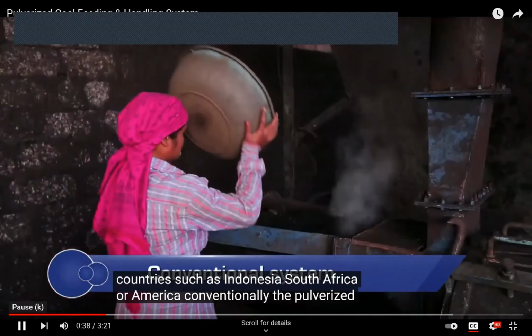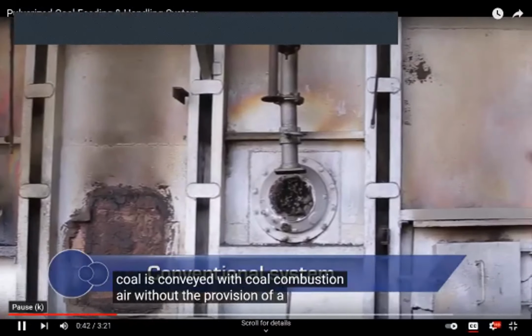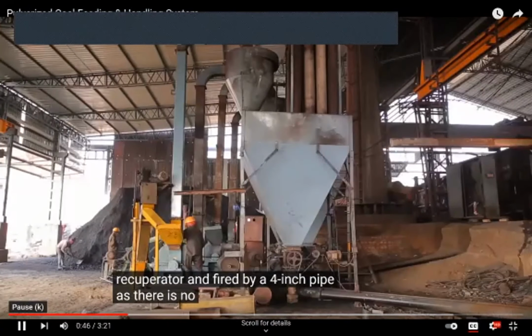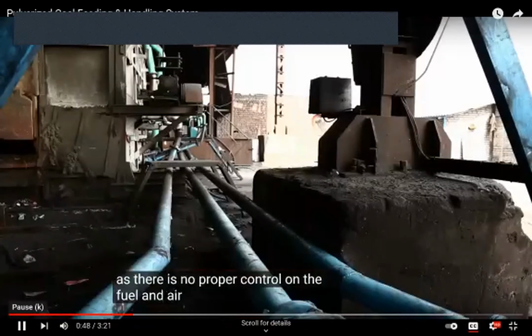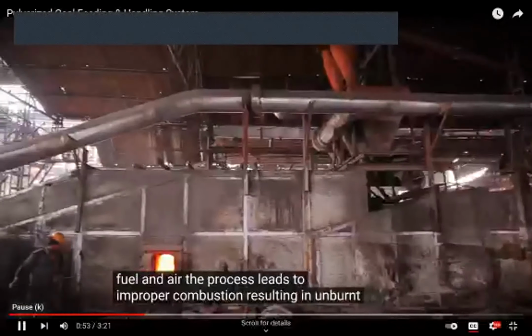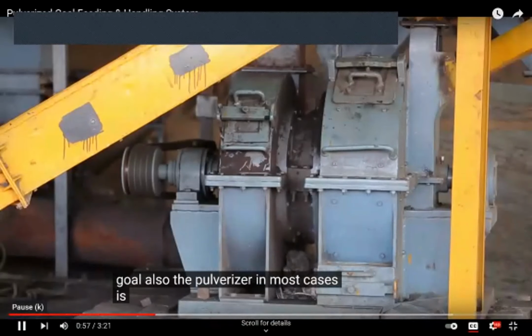Conventionally, the pulverized coal is conveyed with cold combustion air without the provision of a recuperator and fired by a 4-inch pipe. As there is no proper control on the fuel and air, the process leads to improper combustion, resulting in unburnt coal. Also, the pulverizer, in most cases, is inefficient.